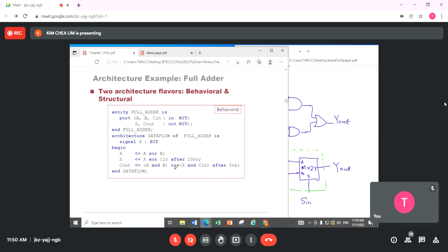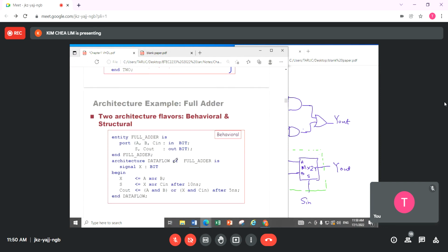This part here, well, I think can finish this one. Okay, so another example, full adder, which we have the entity one. So you find that now make a more complex, more complete design here. My full adder, we start off with this. I think I already described to you all here. Entity full adder is, I got 3 inputs, 2 outputs. Finish this part. After this, I have my architecture. Now I want to use the word data flow.